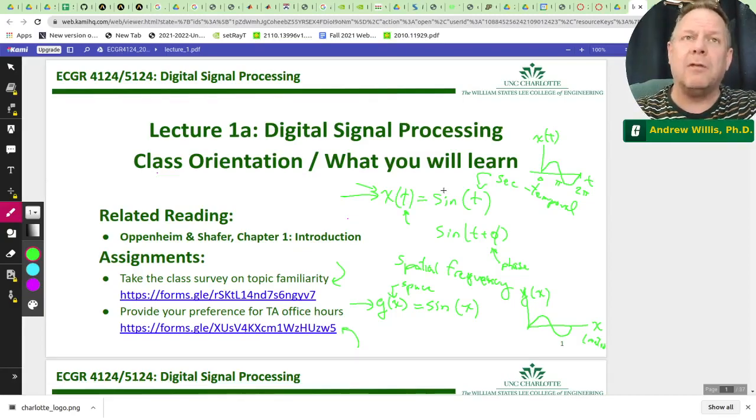So if you're trying to use visible light as a sensor to help drive a car, it's going to have a problem when it snows or when it rains. And radar doesn't have such problems due to what they call Mie scattering. Mie scattering is the relationship of the wavelength to the objects that might scatter that electromagnetic radiation.